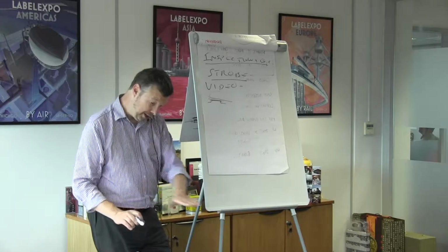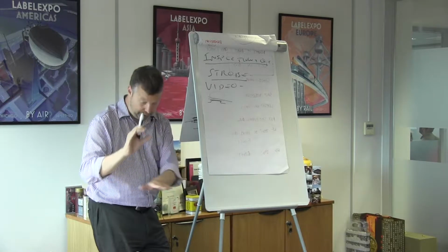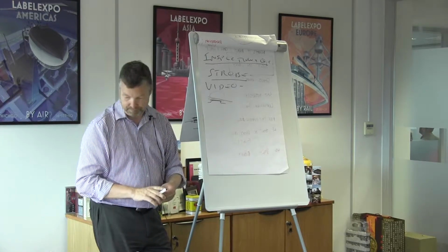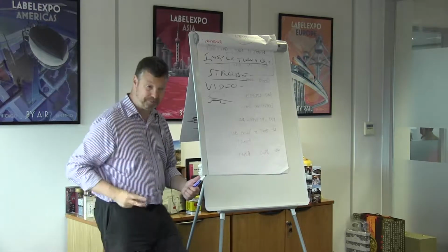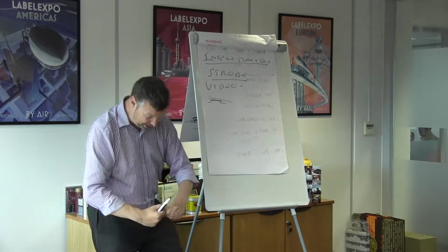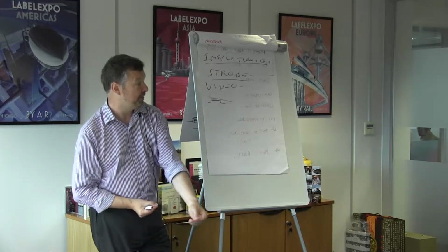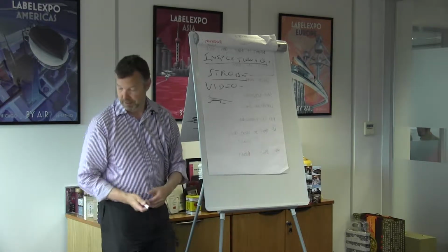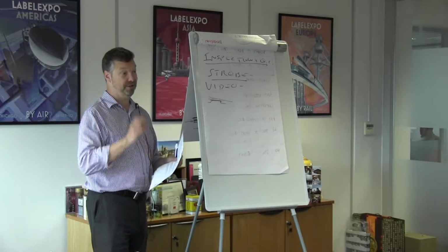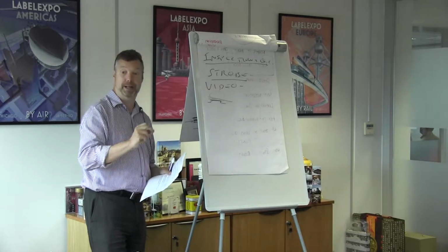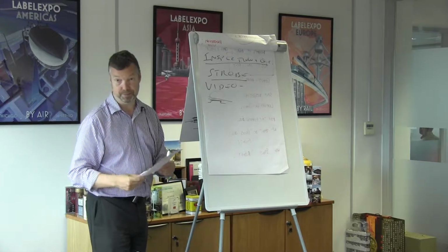And if they see a bad label come along, or the camera tells it's a bad label, then they slow it down, have a look, stop it, get a pair of scissors, cut it out. It's all pretty crude stuff. Then they splice the web back together with a bit of tape, and off it goes again. So the idea is that the rewinder operator is taking off all the bad labels before they get to the customer.